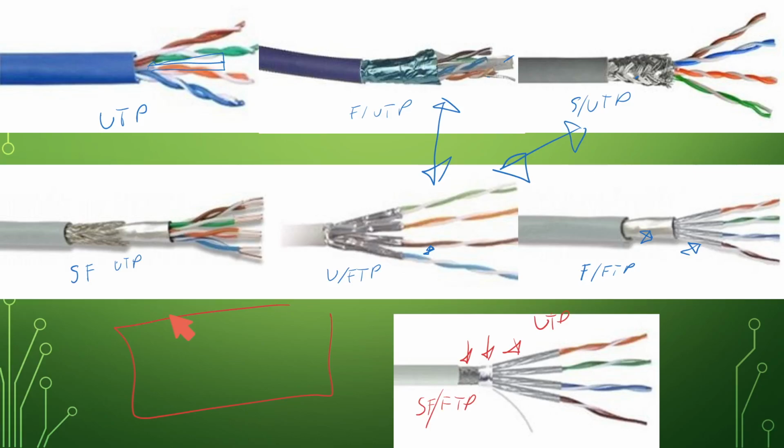Not only that, but all the power wires go into it. So I've got to get to the control panel for that thing, which means I've got to get in the room with it. But I'm going to have this giant EMI spike around it from the motor turning on, plus all the power wires going into it are going to be producing their own EMI because of the power voltage drop or whatever. That could just absolutely screw your communications for a few minutes as that thing ramps up.